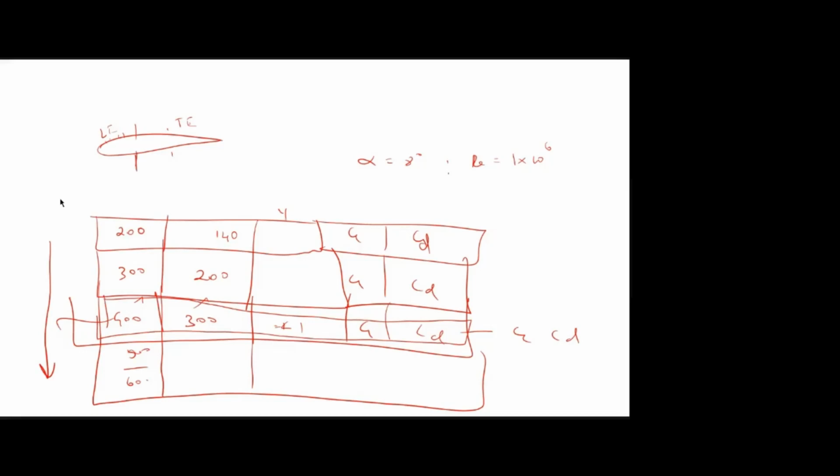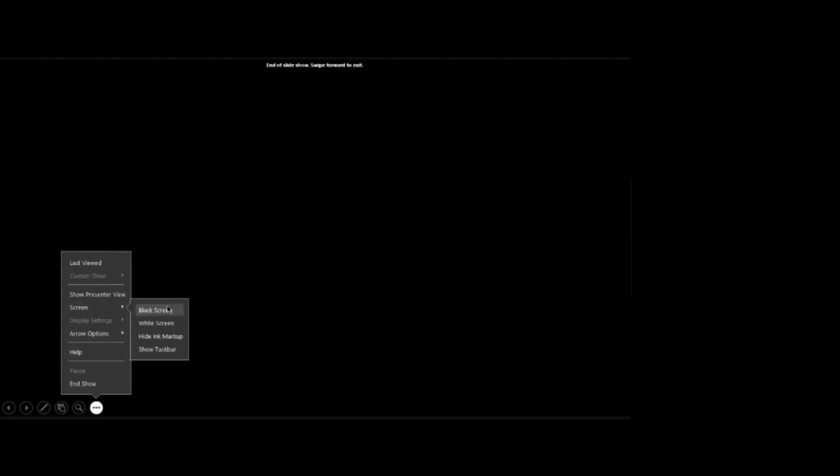It happens based upon what technique you're using to create the split. If the cutting edge is not proper, it will lead to two overlapping phases. Sometimes it will not show you an error. Only when you import it and do the meshing will you realize that there are two different meshes in the same region. Only then will you be able to identify it.